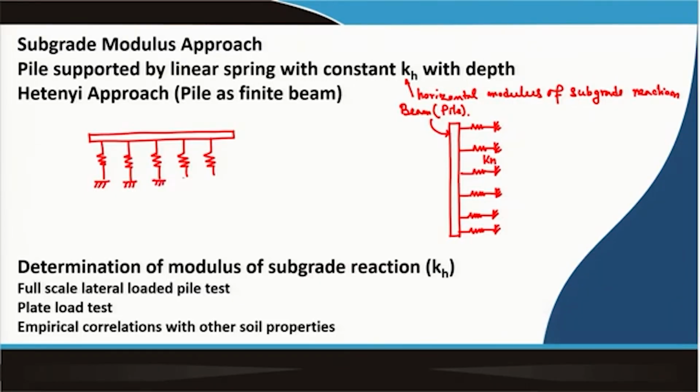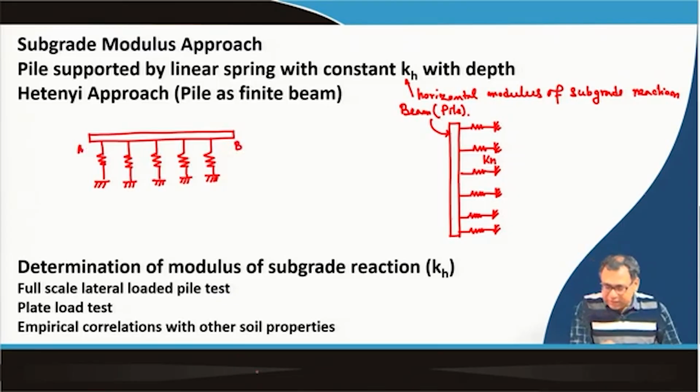Now, if we model this, I have already discussed that for different end conditions we have to consider some end conditioning forces, say P0, M0 or P0A, M0A, so that the boundary conditions can be satisfied. So, the first condition in this finite beam problem is that we assume both ends are free.